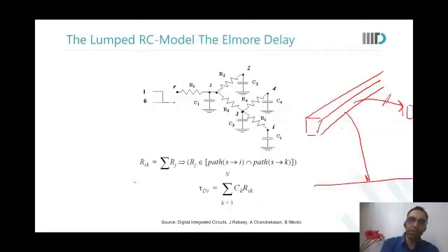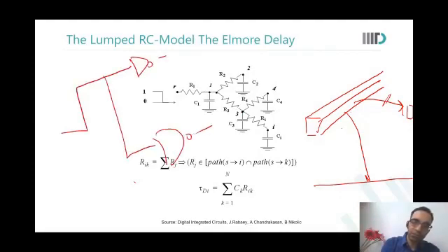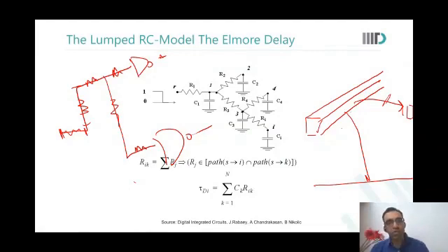So what you say is that I had this wire going from here to the inverter, and then it took a turn, it went into a NOR gate or something. So a distributed RC network would say, I would want to make an RC of this, a separate RC of this, RC of this, RC of this, and so on. And this I have just shown as a schematic view. As soon as I make the layout view, you will see the metal would have moved from metal 1 to metal 2 through a via 1. So all those transitions, you will see. So when you do post-layout extraction, in the first extracted file you will see there are so many resistances and so many capacitances because at every via it is taking a break.